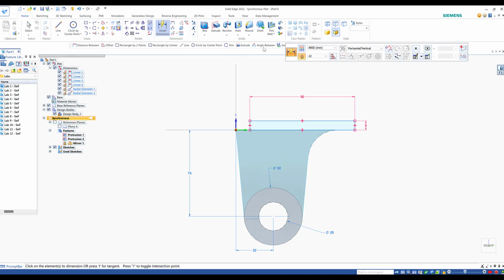And then I'm going to correct the location by using the X command, and the X from here to the coordinate axis. This distance should be 0. I'm going to make it 0. Okay. Very good. So we got this one. And the next step is what? We're going to do the extrusion 180.